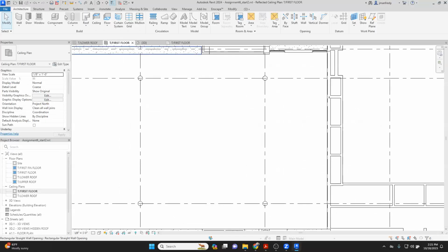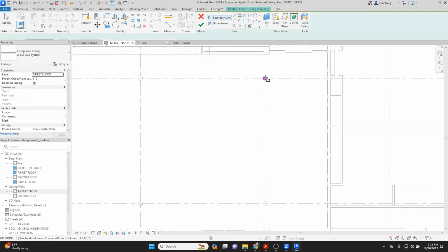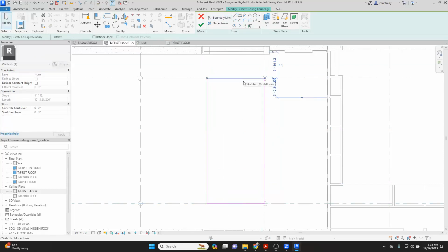So if I draw that shape as a ceiling temporarily, an acoustical tile ceiling, I sketch it out. You can go from the center of the column, and you can make an adjustment here. So this thing here gives me a weird dimension, but I'm going to click on that little dot and drag it down to here. And that tells me it's 33 feet. I want it to be 32 feet, right? So I just type 32.